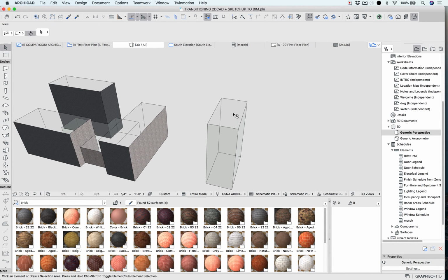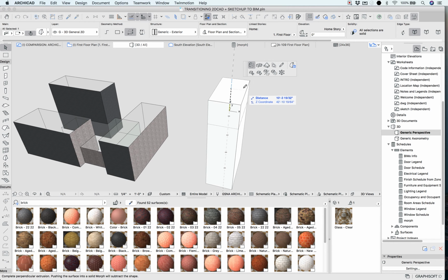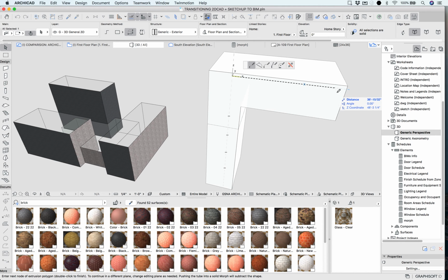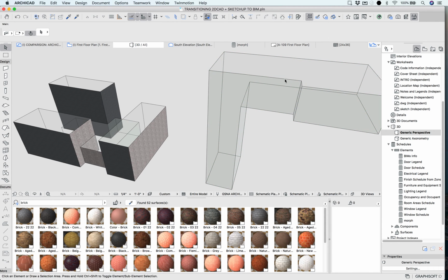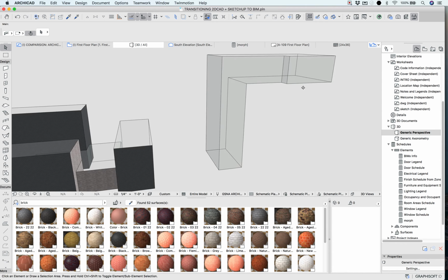If you're using a SketchUp workflow, you can select the face, and maybe you want to go into what we call a tube mode, very similar to a follow me mode, and you can continue drawing still very freely. So, we use this morph tool for object creation, as well as to explode elements. So we'll talk a little bit about bringing in SketchUp elements as well.